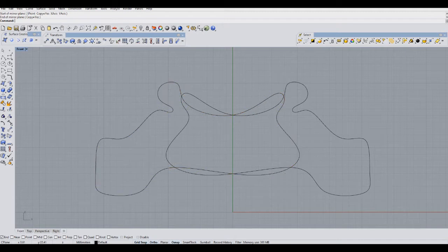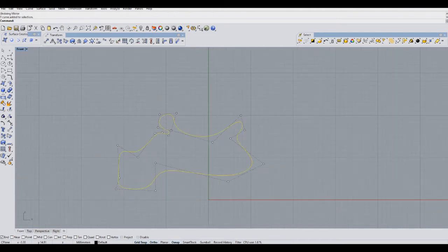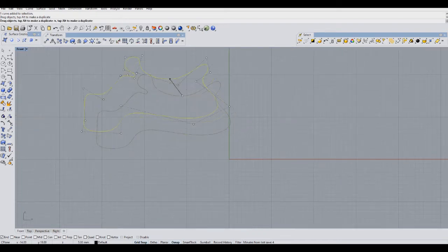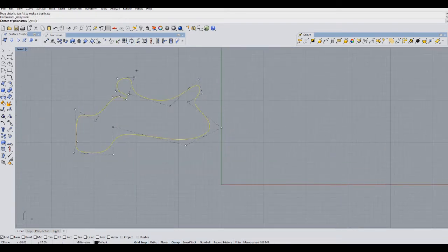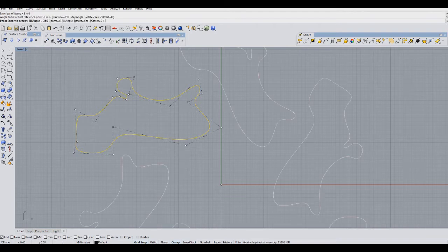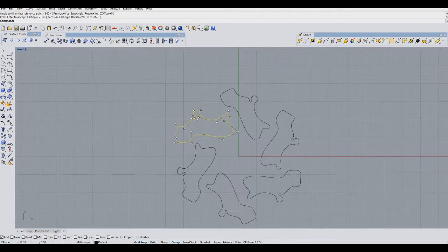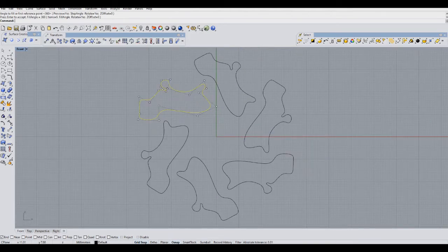That's one major command that I'm setting as a ground rule here. Another one would be the polar array. That's a command I use very frequently for shapes that have a lot of copied sections. So if I array it around a central point, let's say 6 times, that would be the use of the polar array command.